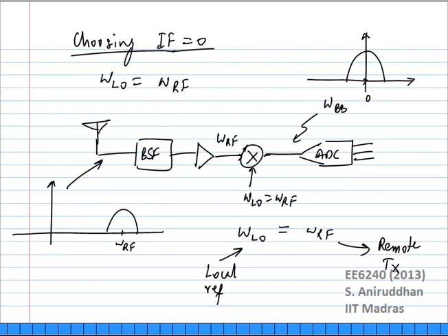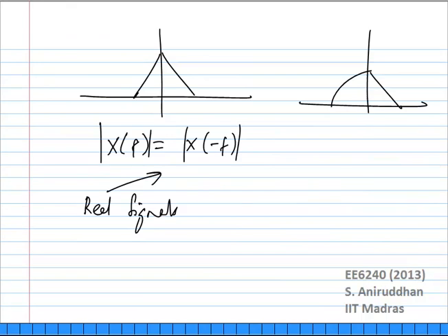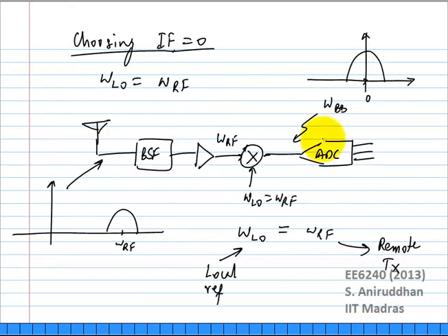Low frequency noise. Remember we talked about flicker noise yesterday, right? So you have a receiver with, let us say, even this ADC, okay, or if you had an amplifier here, or any kind of filter or anything you have here at baseband, okay, what will happen is, I am going to have flicker noise, okay. At low enough frequencies it is going to dominate, it's going to kill the SNR of my signal. Okay? How do you solve this?